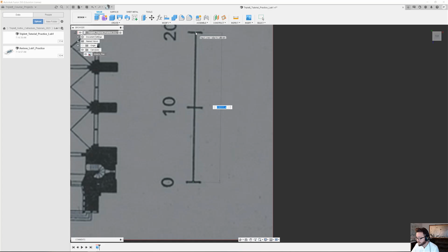Okay, and what it says right now is that the scale is 0.003 meters. The reason it says meters is because of my document settings, you can double check that it is already set to meters. What I want to do is, without touching anything, I'm just going to type 20 meters, just 20, and hit enter.